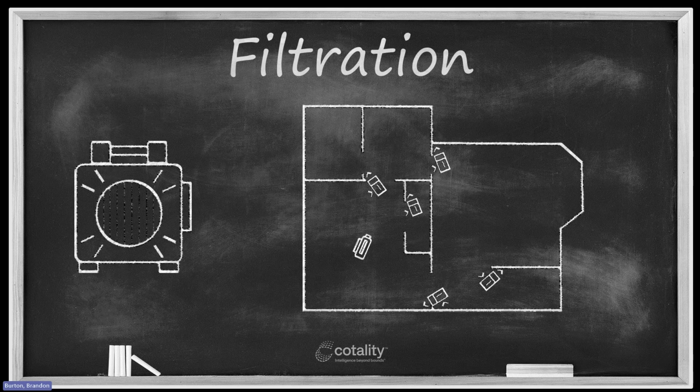What I need to do, and what I find to be most practical, is to put the air filtration device more out towards the center of the room, because what tends to happen if you've got a laser particle counter, hold me to task on this and try this. This is what I've observed, is that as soon as I get this kind of rotating airflow established around the perimeter of my rooms, my particle count becomes much higher in the middle of the room than it does around the perimeter. That tends to be where my dust starts to settle out.